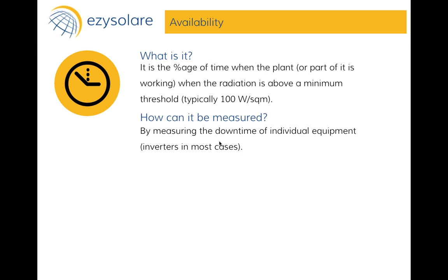But let us go by the performance ratio route. What does that say? Again, applying the same formula that we had applied earlier, the performance ratio actually goes down. So while we were supposed to have a 5% increase, we did not have a 5% increase in the generation. The radiation went up, but the generation did not. So the performance ratio actually went down from 78.2 to 75.4.